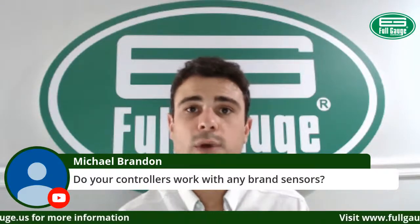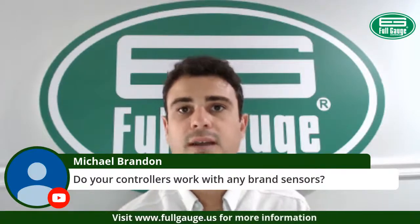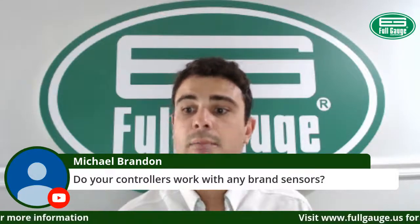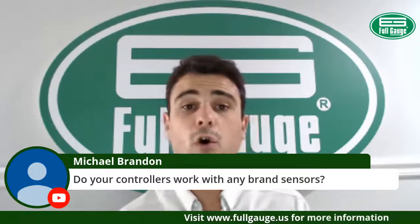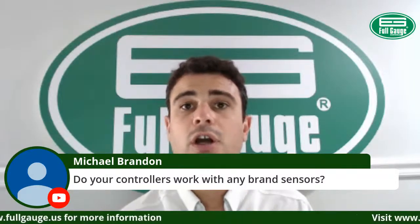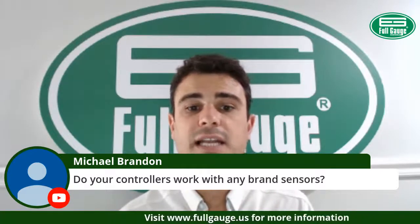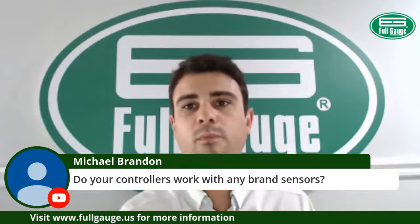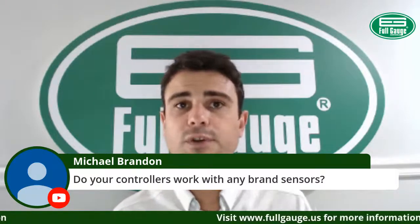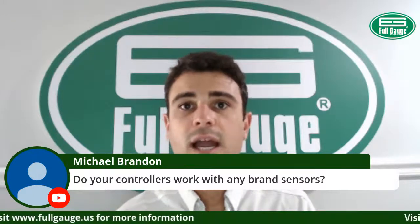However, outside the 25 degrees range, you might have a temperature difference because the curve is not the same for every control manufacturer. But our controllers provide you the offset option, which allows you to adjust any temperature deviation that might have been created by a different sensor. Another alternative is to strip the tip of the sensor and connect our tip.